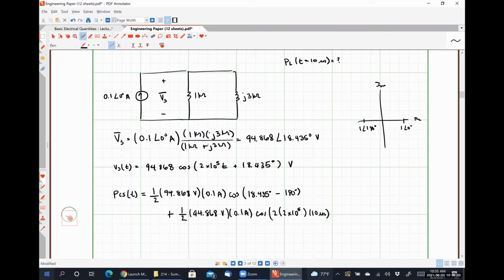And I'm about to do another conversion here, and it's very, very important, okay? Omega is measured in radians per second. So I need to convert that to degrees per second in order to add my phase angle in, right? Because if I try to add radians and degrees at the same time, it's not going to work out well for me. So my conversion factor here is going to be 180 degrees per pi radian, which is going to give me my angle in degrees.